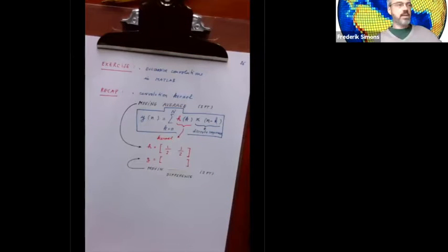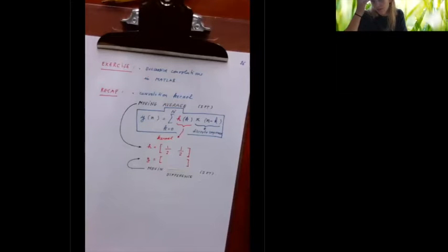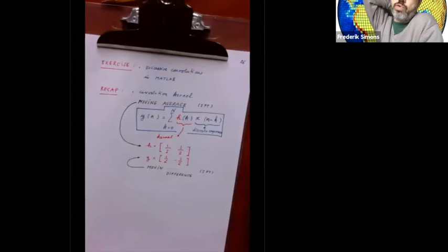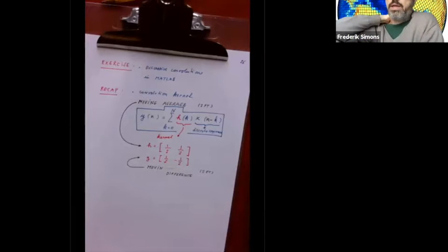Now my question is going to be simple. What's the convolution kernel for a moving difference? 1/2 and -1/2. Yes. Just like the moving average produces a sequence where every number is the average of two numbers. If I start counting at 1, the first one is the average of 1 and 2, the second one of 2 and 3, of 3 and 4, and 4 and 5, and 5 and 6, and so on. Now, switching the sign, I will turn it around and say, give me the moving difference of 1 minus the second one, and then the second one minus the third one, and the third one minus the fourth one.